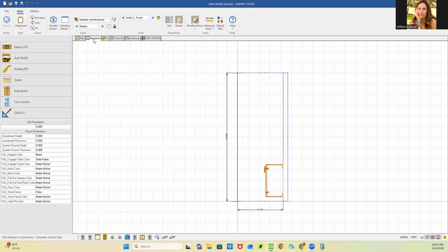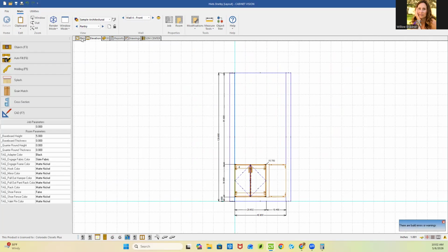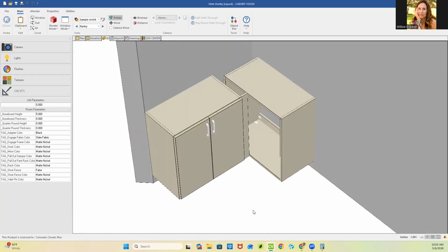Okay, so how would you word that? Bring in the cabinet that's going to remain the most standard, or bring two cabinets in at the same time? I put my actual corner cabinet, the one that dives into the corner, and then I'll put my opposing cabinet on the opposing wall. I'll get my opposing cabinet set up because it's basically just a normal cabinet. Then it has a filler that fills in the gap, and I make sure that filler is the size I need it to be to create the reveal on that corner that we're going for.